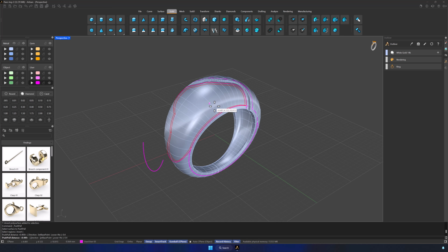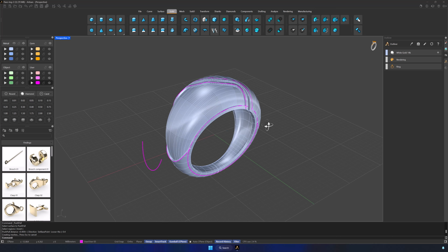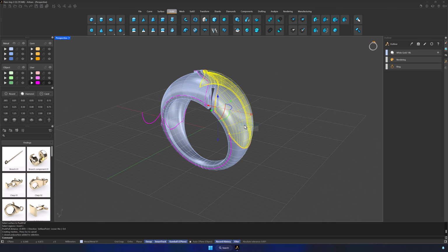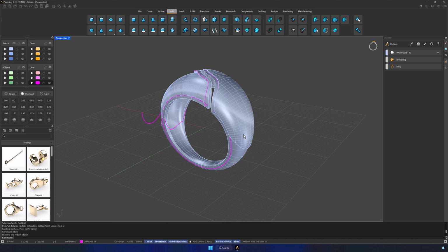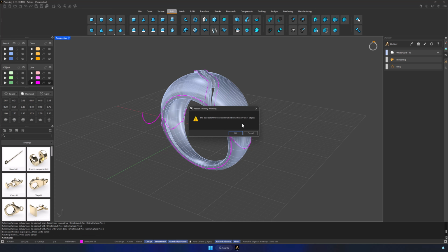As we see, on one side, the Boolean operation did not apply. But that's okay. The solid has been created. Hide the ring and we can see it. Perform another push and pull, but this time, move it upward by 0.2 millimeters. Restore the ring and perform the Boolean operation. Select the ring, then the solid. Now, our base is complete.